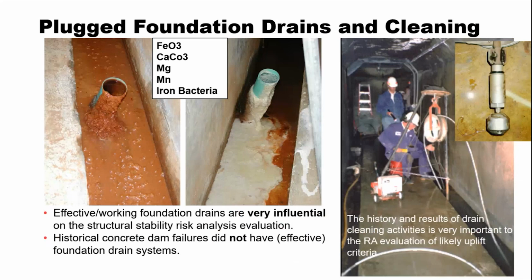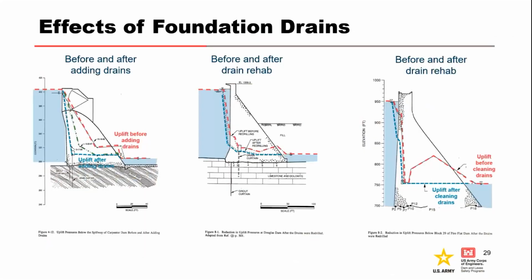So it's important that we keep the drains clean and efficient. The right image shows high pressure drain cleaning being used to clean the foundation drains from a concrete dam gallery. And then these pictures show how adding or cleaning drains affect the uplift pressures on the dam. The red line represents uplift pressures before adding or cleaning the drains, and the blue and green lines are after adding or cleaning the drains and show a substantial reduction in uplift.